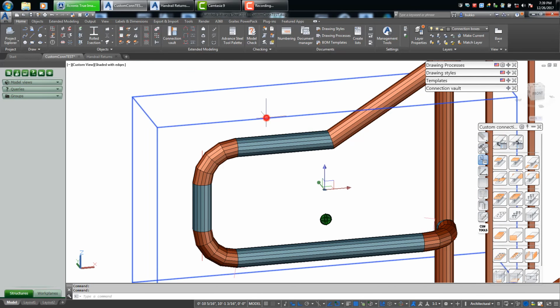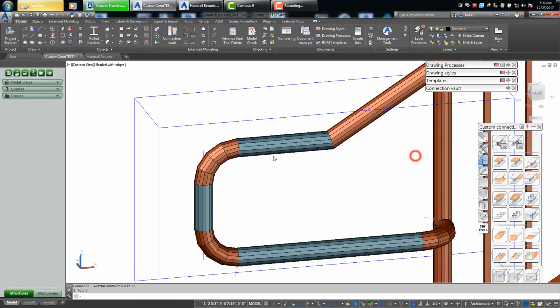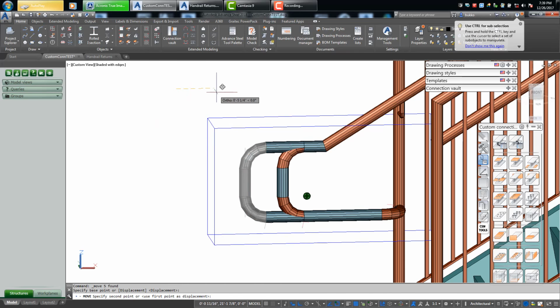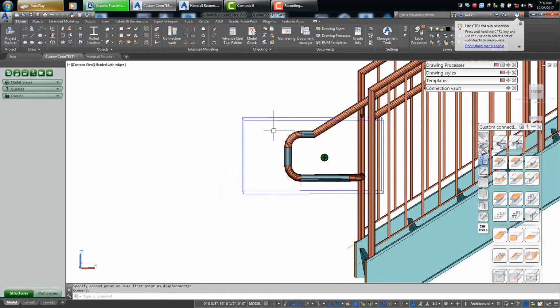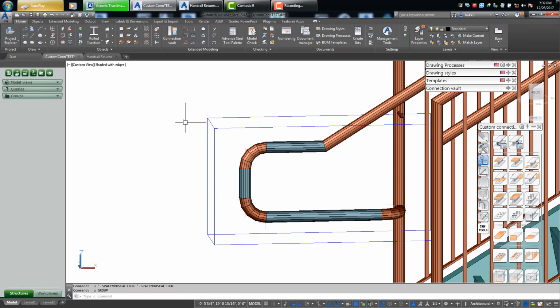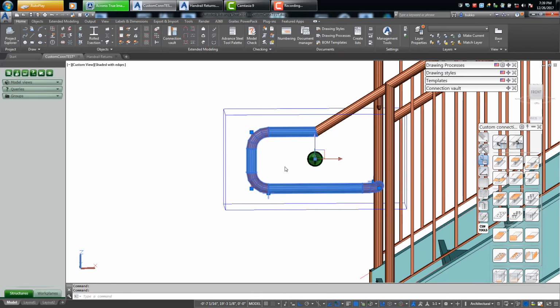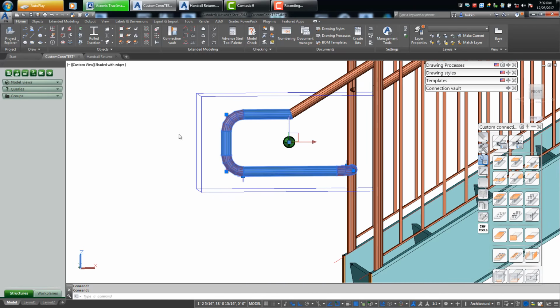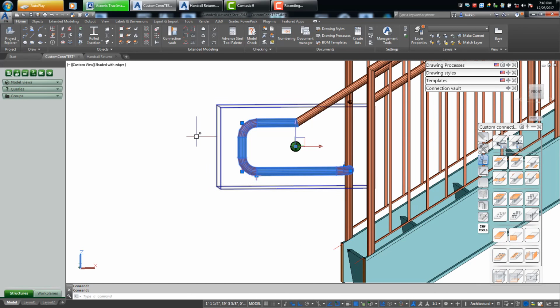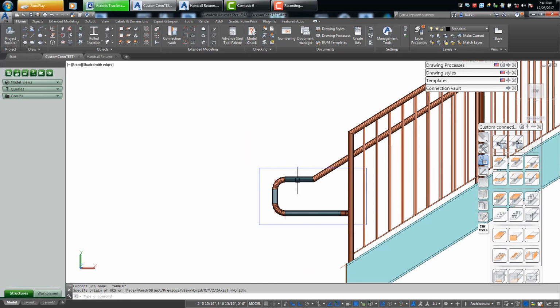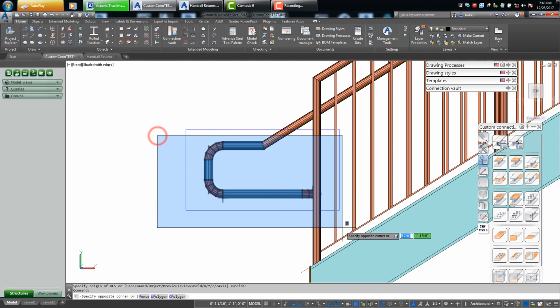You can allow for modification, and then again, if I want to adjust the distance, or even the height, actually, I'm going to go ahead and try the height here. Let's say that you have a different riser height other than 7 inches here, and you want to adjust it from 35. Let's say that you're using a different stringer, for instance. Let me go ahead and get my universal coordinate system where I want it. I'll select the entire group.